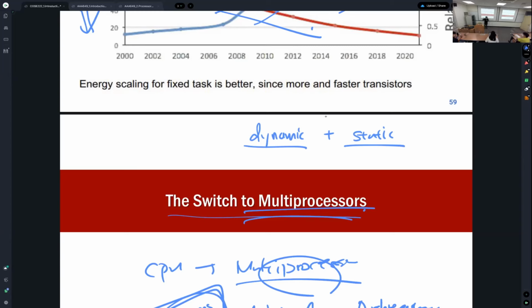The CPU generates an output of 0 or 1, and this output is changed by input signals, which are also 0 and 1. Electric power is consumed when input signals change, but also when the output signals of a circuit change from zeros to ones or ones to zeros. This power consumption is called dynamic power.